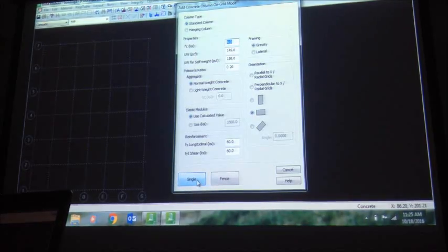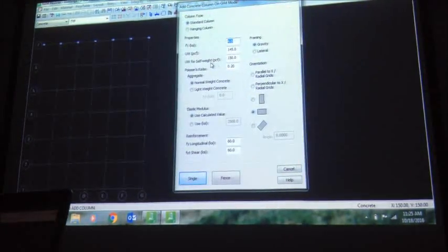So you can go and select single. If you see, it will snap on the intersection. So if you click on those, it will snap them. Now it's pretty much time consuming. Okay, well, not that much, but still. So if you right click on your mouse, the same dialog box will come back. And instead of single, you can say I will do it as a fence. So click on that. Fence it, it will place columns everywhere. Okay, all intersections. So my columns are placed.